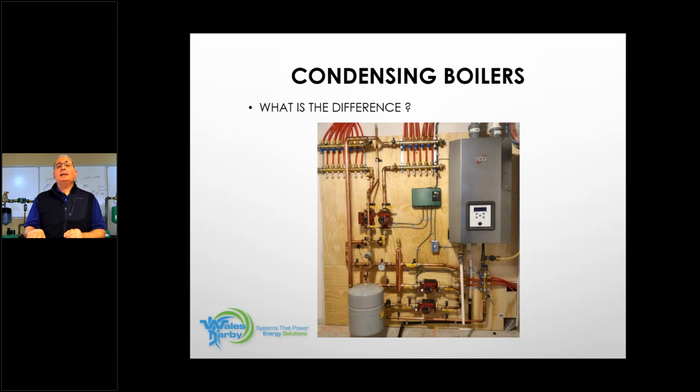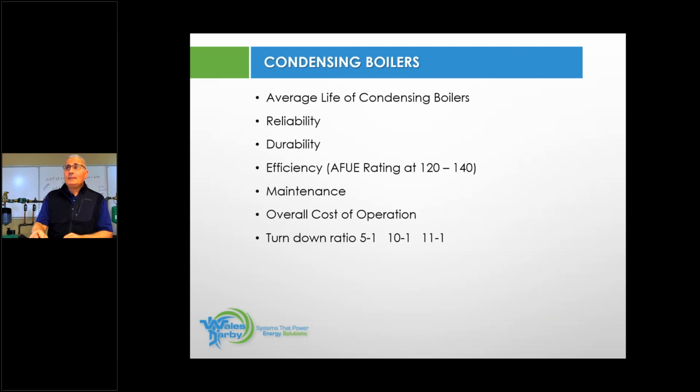But these boilers are going to condense. We want them to condense. You guys already told me how they're going to condense by having a return water temp come back of 130, and that's a big deal.